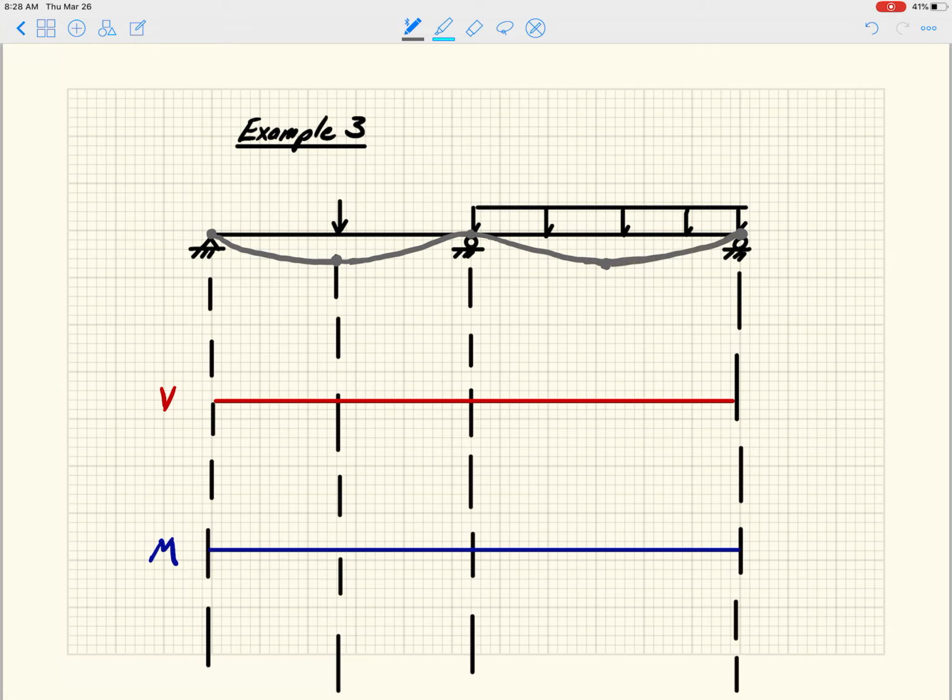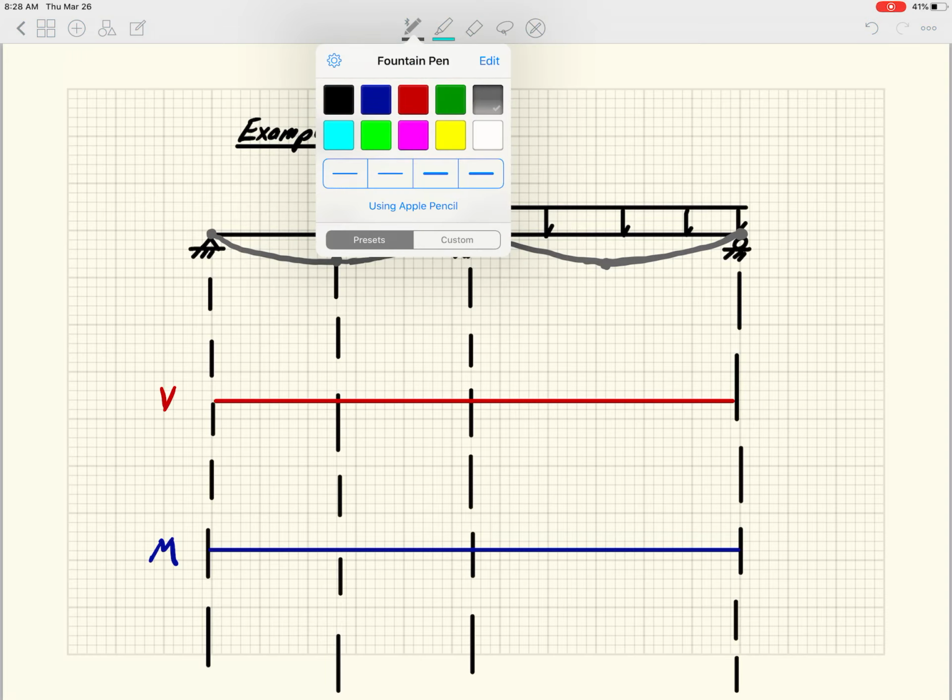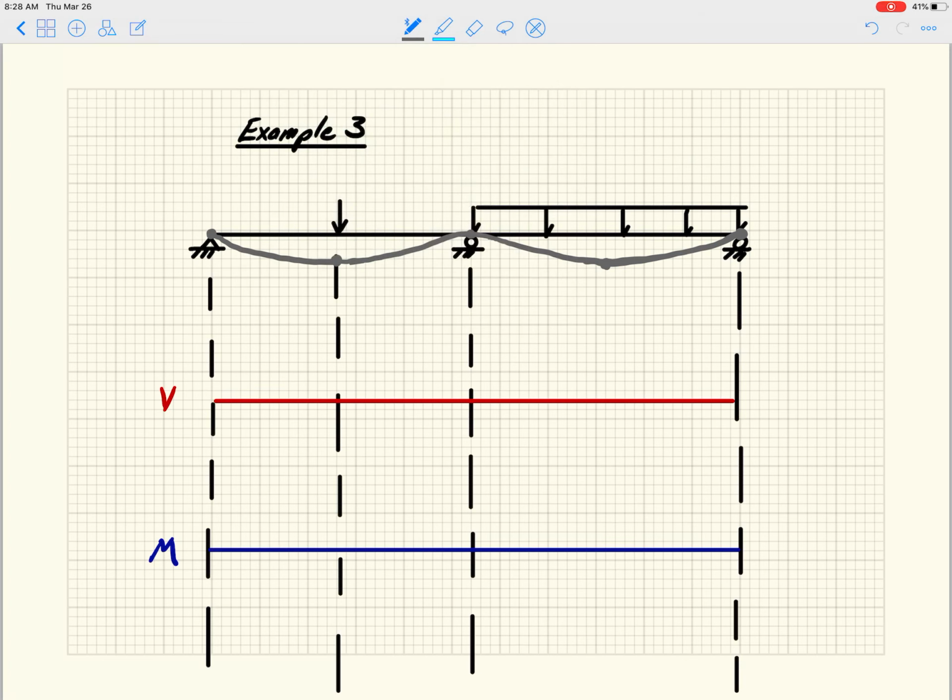And if you notice, what I did here is over that center support, right, I cannot have a kink, right? There's no moment release there. So I do need a curvature reversal, right? And so over that support, I have compression on the bottom, tension on the top, and then here is compression, tension, and here is compression, tension, right?